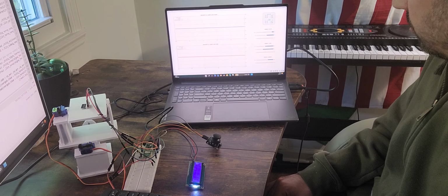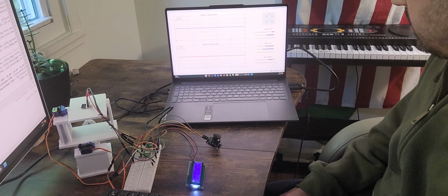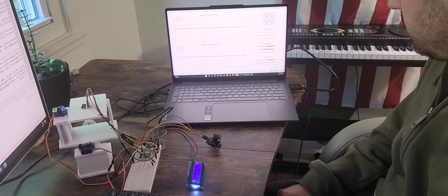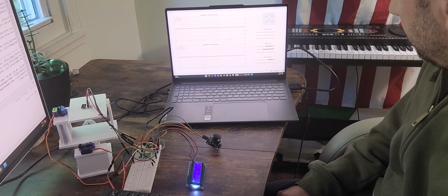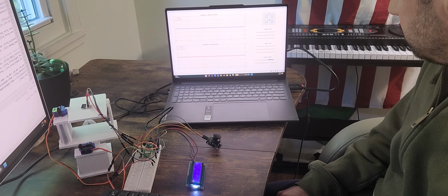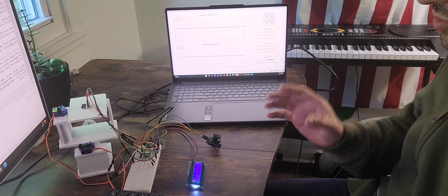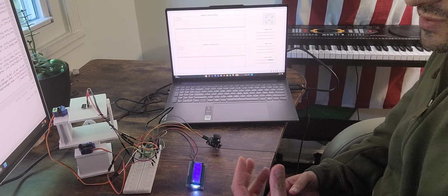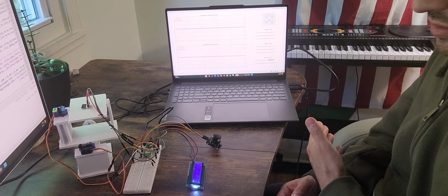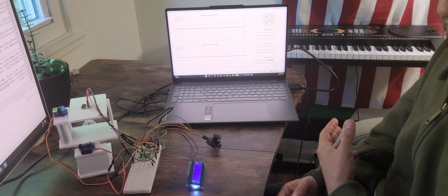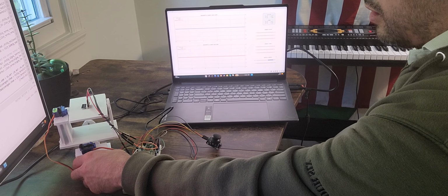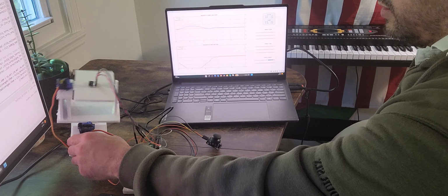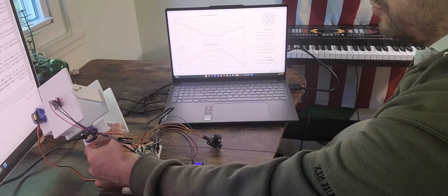So for example, I can actually turn off those gains completely, put them at zero, right? And what that will do is effectively turn off the motors, servos, and that would allow me to, for example, fine tune the complementary filter coefficient. If I take it now, it's not going to move, it's not going to do anything, as you can see, because I turned off the motors.